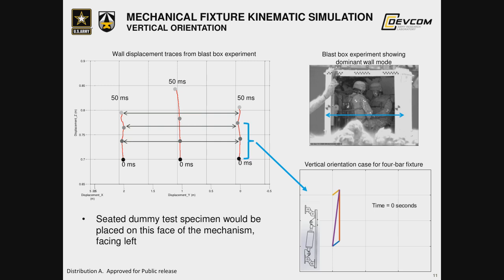And the dynamics of this are, of course, determined by the characteristics of the shock absorber and also the arm, the 4-bar or the bar linkage length. We have a dynamic model that can be a parametric model that can be used to tune to any pulse, so pulses can be simulated in advance of experiment.